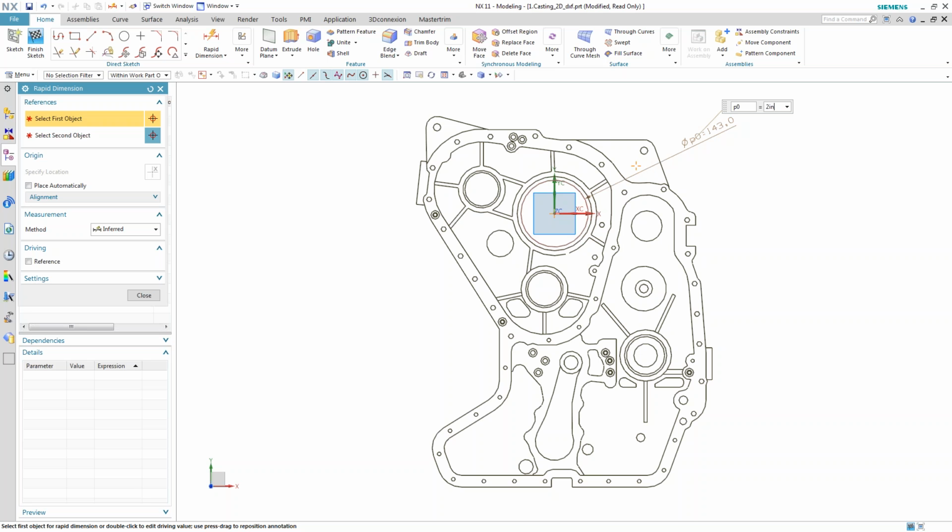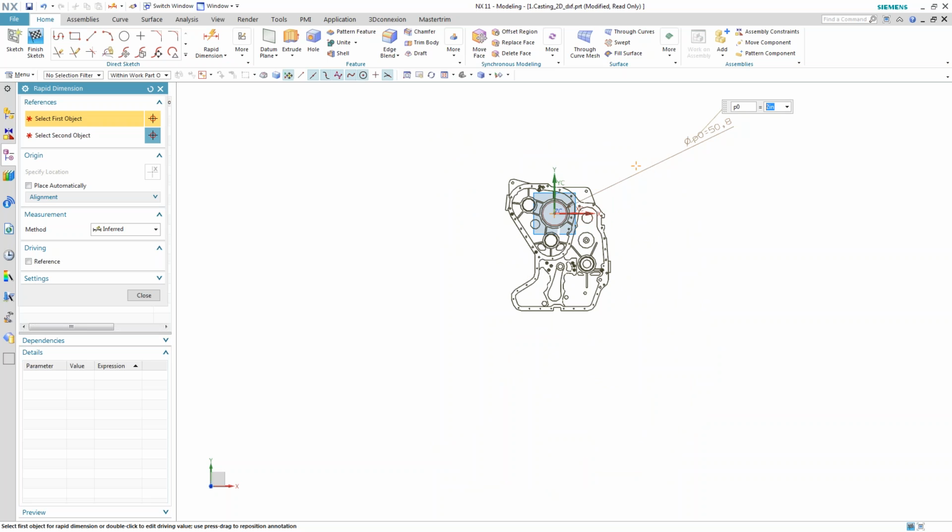In case you didn't know, you can apply inch to metric conversion, metric to inch. So if your drawing is a metric drawing and you know what the inch equivalent is supposed to be, instead of 50.8, I can put in here 2 inches so I know that I'm getting the correct value. And when I do that, you see the whole entire drawing scaled.